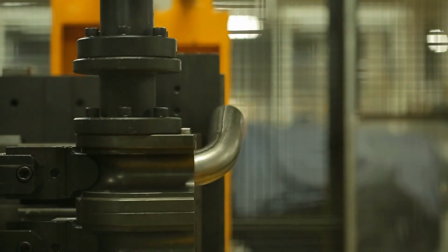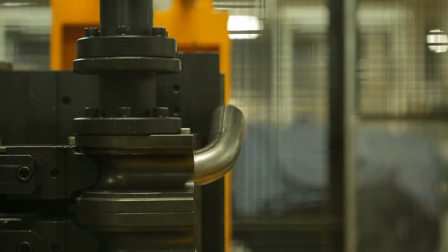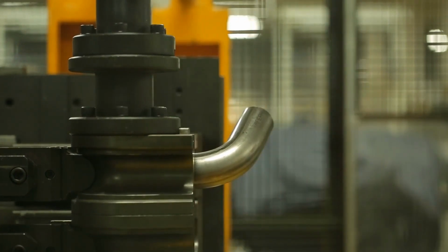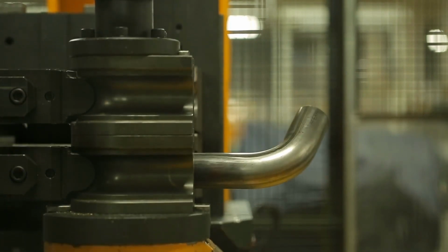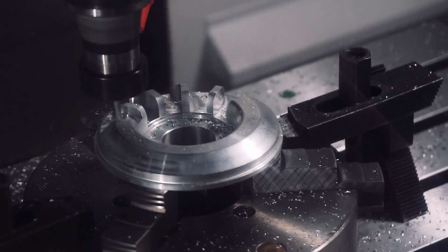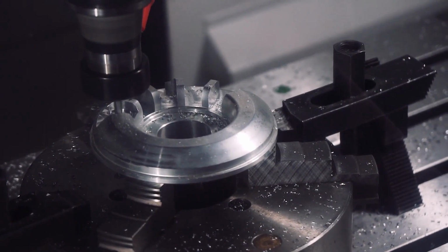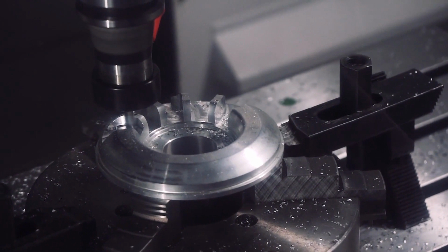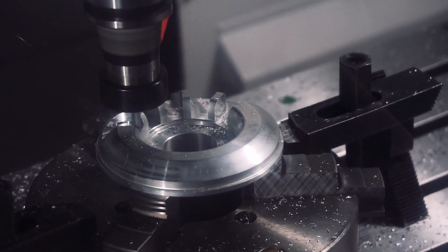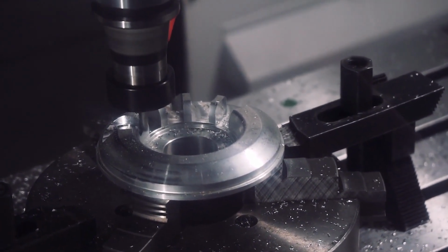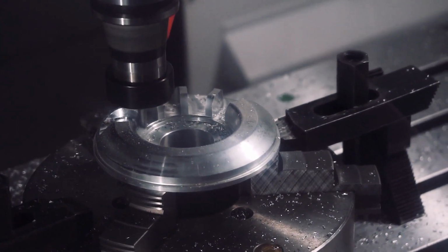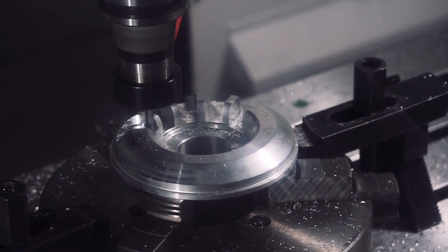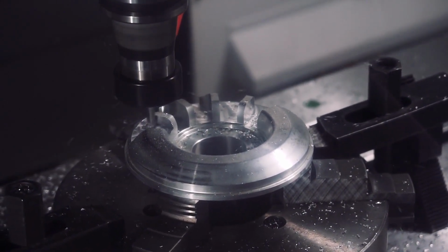How CNC and human coordinates interact. As we mentioned above, human operators will use a WCS, which provides an easy set of coordinates for writing a CNC program. However, these coordinates are always different from a machine's coordinates. So how does your CNC machine line the two up? With offsets. A CNC machine will use a work offset to determine the difference in distance between your WCS and its own home position. Here we can see that several offsets are programmed: G54, G55, and G59.